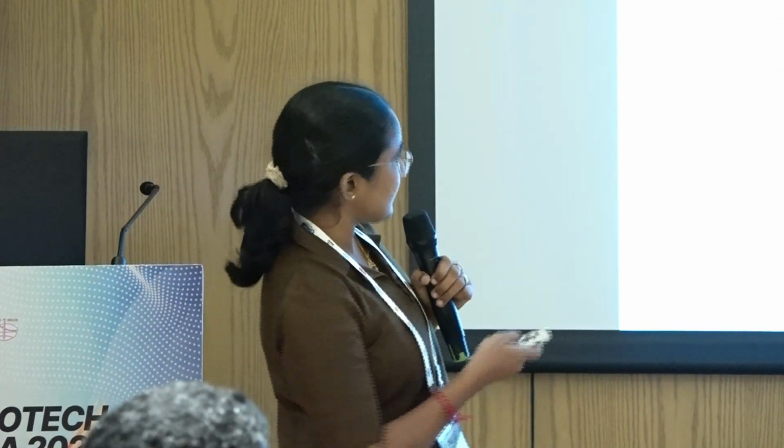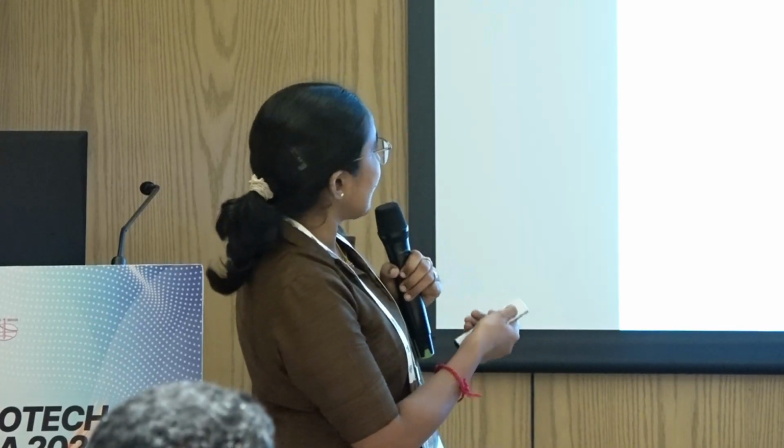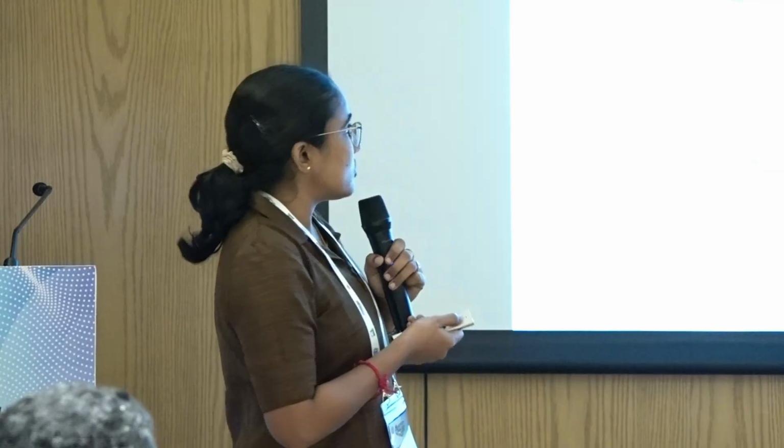So SEM analysis also showed that it has coated over the mica particles. So this xanthan gum biopolymer tends to surface coat the mica particle, which resists the crushing effect. In that case, this is also giving a binding effect in its as compacted state. So that was one observation we have made.